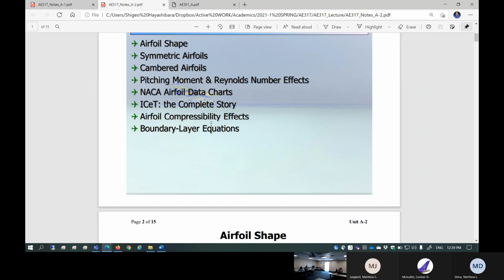Plus, if your airplane is a high-speed airplane, you can correct for compressibility with Prandtl-Glauert. So three things are hovering around right now: the core solver, which is the panel method. If you want to add a boundary layer model, you turn on the viscous model, and then the boundary layer model is added on. If your airplane is more than 0.3 Mach, turn on the Prandtl-Glauert correction, just add on. That is your solver XFLR5.